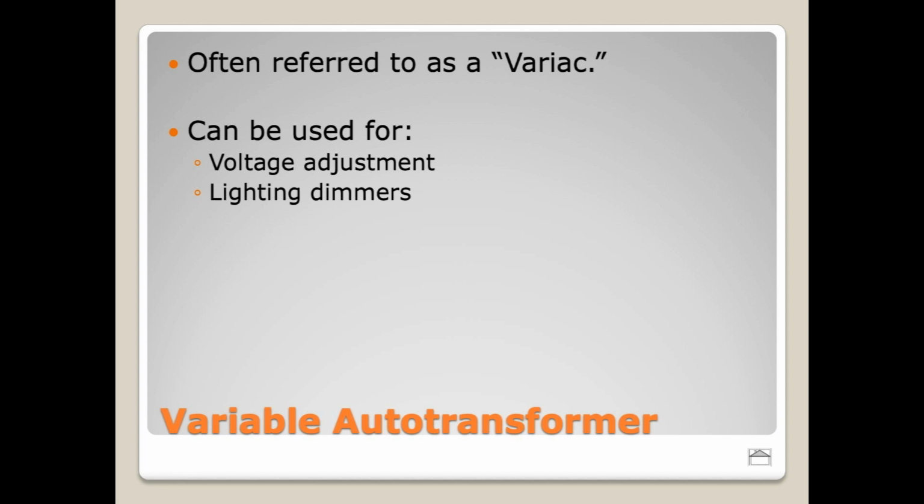Now, we haven't talked about those yet, but capacitors are essentially small short-term batteries that store a charge for a brief period of time, sometimes very, very short periods of time, talking in the microsecond range. But they are very critical to the way the device functions. And if they've been sitting dormant for a while and you simply hit them with the full voltage that they're normally operating at, you run the risk of damaging them or destroying them.